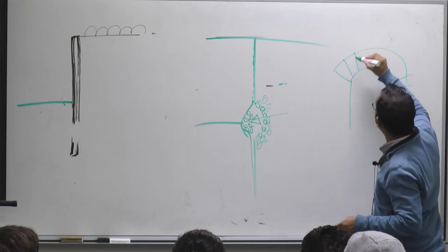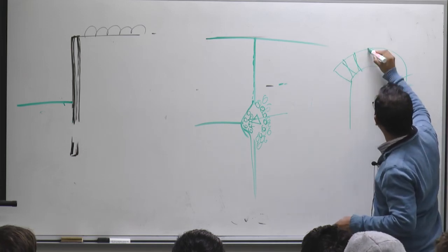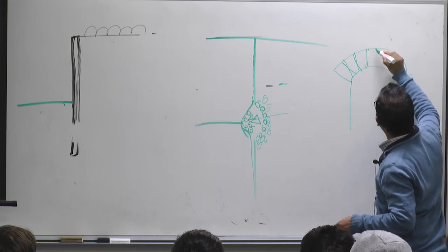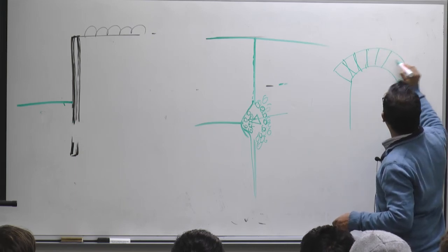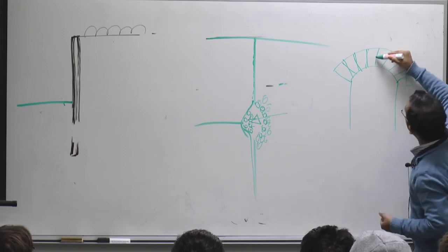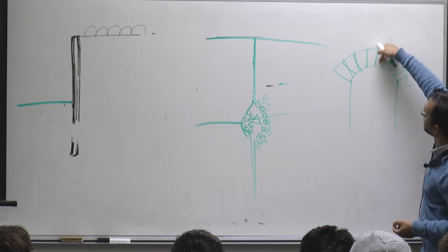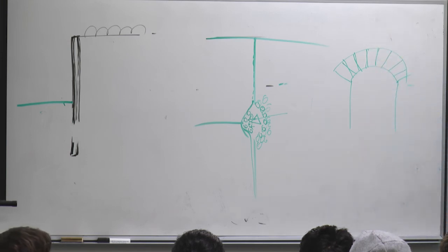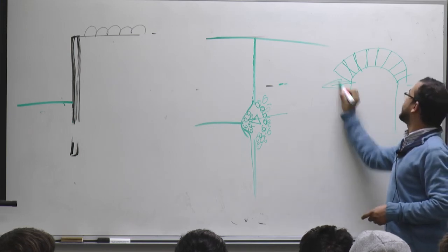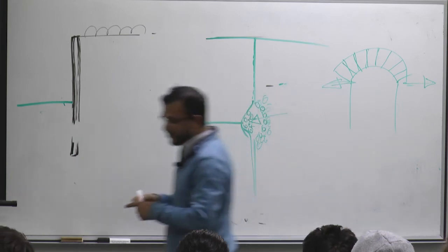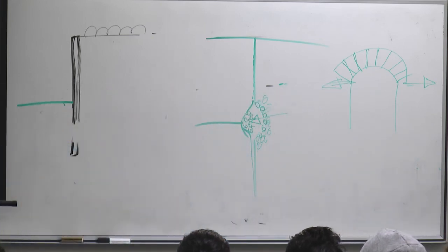If you put some blocks, because of their shape, this thing cannot go in. It cannot fail. It will hold itself. So it gives lots of lateral pressure, but it is stable in the vertical direction. So this kind of structure, you do not need any reinforcement.